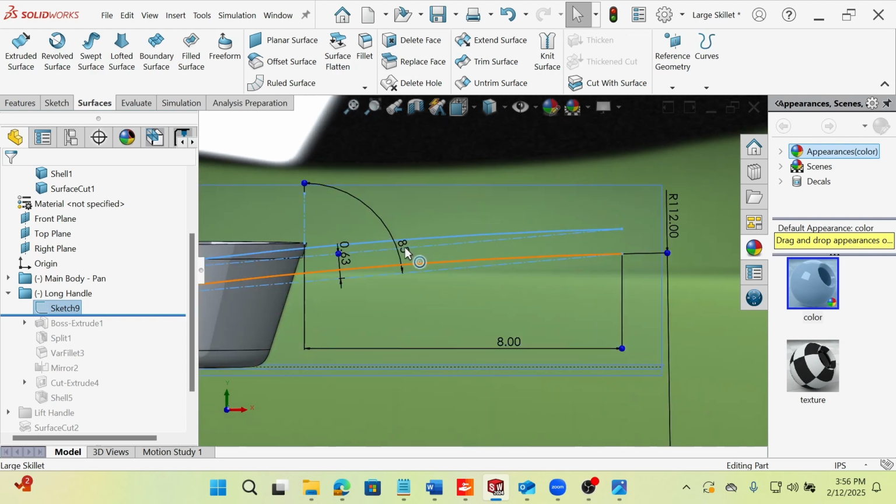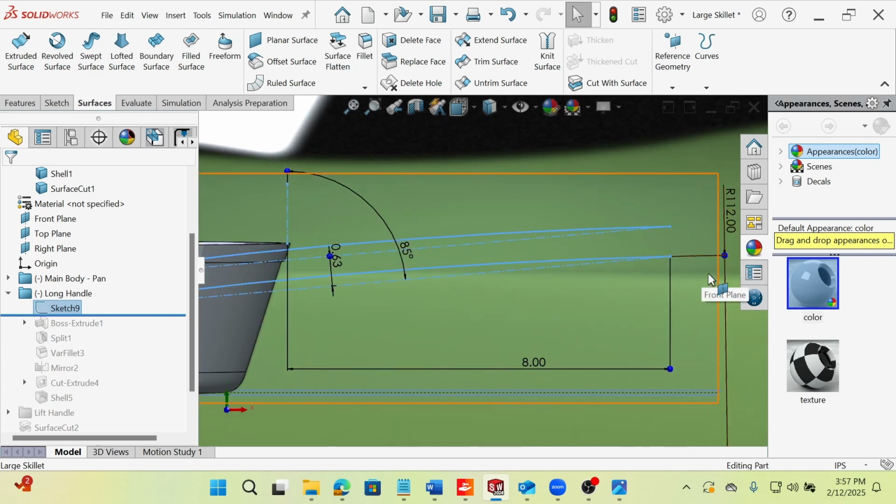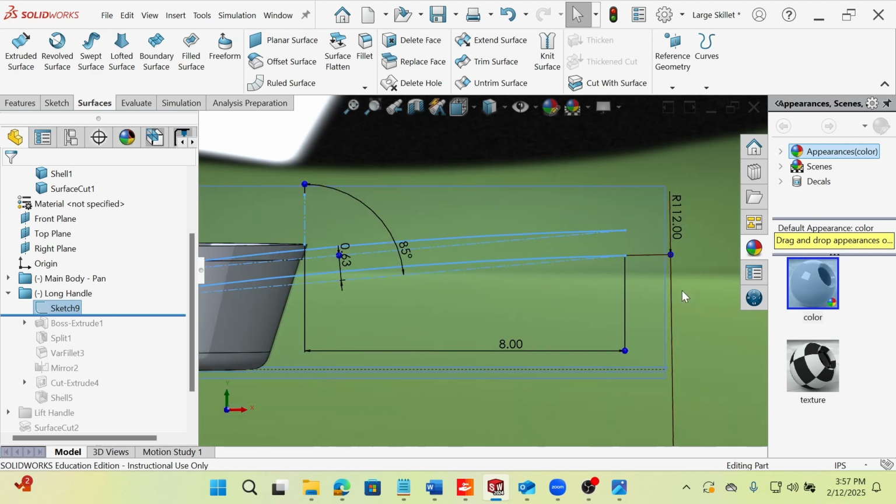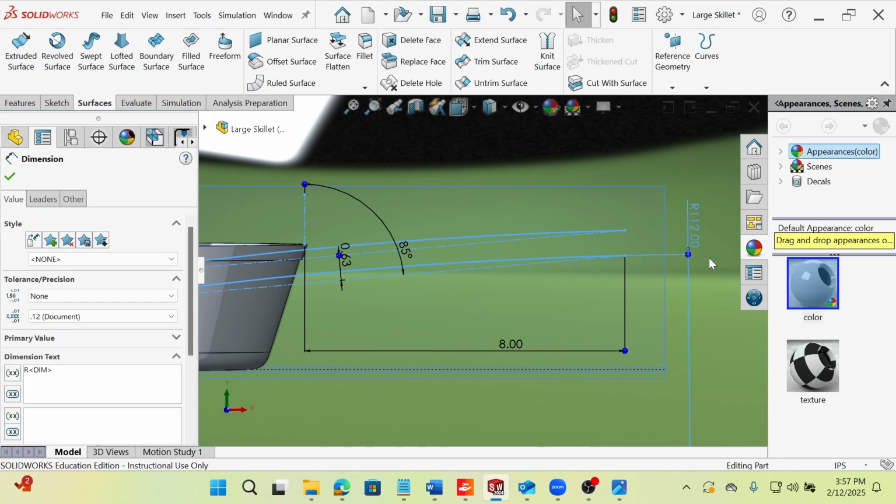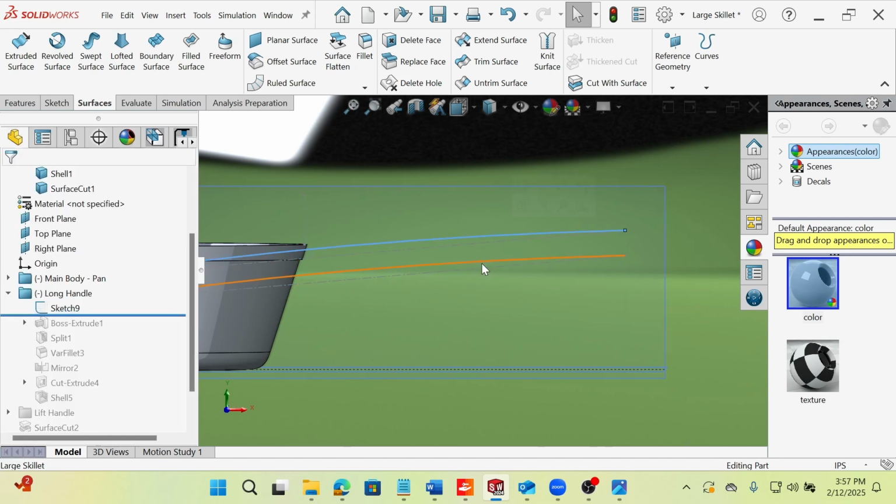Now, we may need to shift these to just a straight flat design to accommodate for ease of molding these items that you guys are going to do at the foundry. But just consider that. We'll get into a little more manufacturing constraints later. For this is a concept execution, and this happens a lot of the time in the real world. You'll have an idea and you're not sure if it's completely manufacturable, but you want to get the first version of that idea out there, talk about it, talk about some of the constraints and some of the cost benefit of executing your design this way.